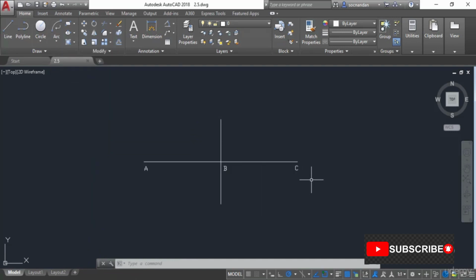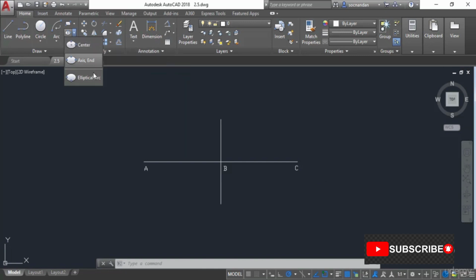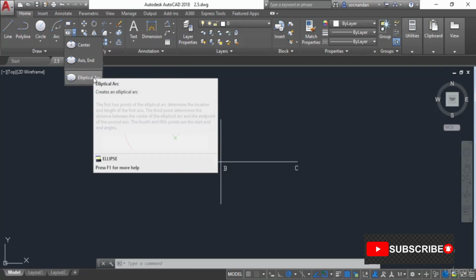In this video, I'll tell you about making ellipses in AutoCAD. So ellipse is a simple mathematical curve, and in AutoCAD you can make it directly with the ellipse tool. So on the draw panel, when you expand this flyout, you'll see that we have this ellipse tool, and you can make it using these two options. We also have an elliptical arc that we will also look at in this video.